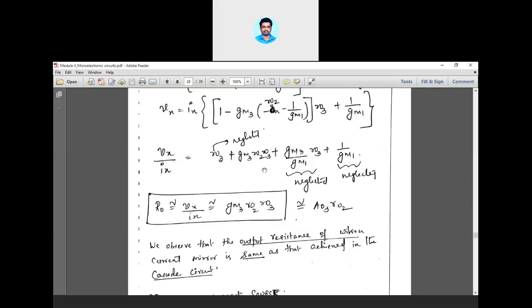So I repeat all the four current mirror circuits that you have learned in this module. First one was the cascode MOS mirror. Second one was the bipolar mirror with base current compensation. Third, Wilson's bipolar mirror. Fourth, Wilson's MOS mirror. The main difference between these four circuits is that even though they are acting as perfect mirrors,